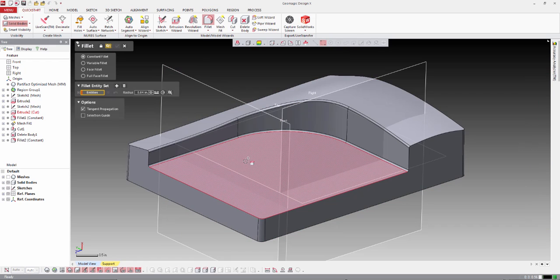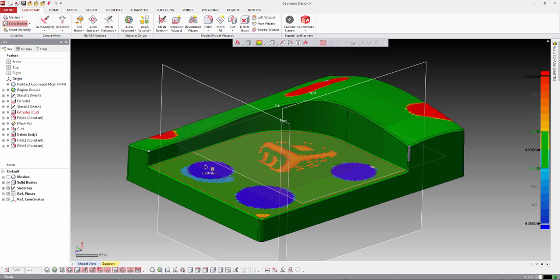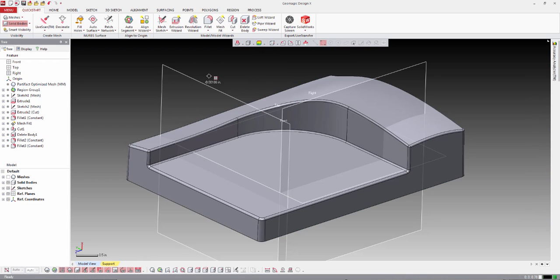I might as well finish out some of the other fillets here. I can run it off of this side, estimate the value. Value is estimated at 0.048, so I'm going to make this a bigger radius now, 0.05, and see what is left to do. Okay, so the next thing I'm going to tackle is the revolved shapes.